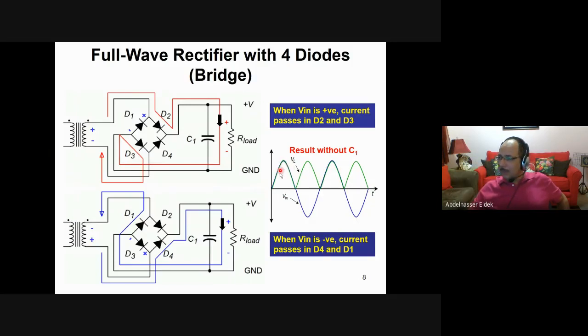So again, if you have a full-wave rectifier, the capacitor will start to charge from here, and then if we are going in a line, we'll go in this direction like this. So it will stop here for the full-wave rectifier. But in the half-wave rectifier, it will continue and stop here. And now we can see the difference between the two signals: in the full-wave rectifier, you have a smoother curve.